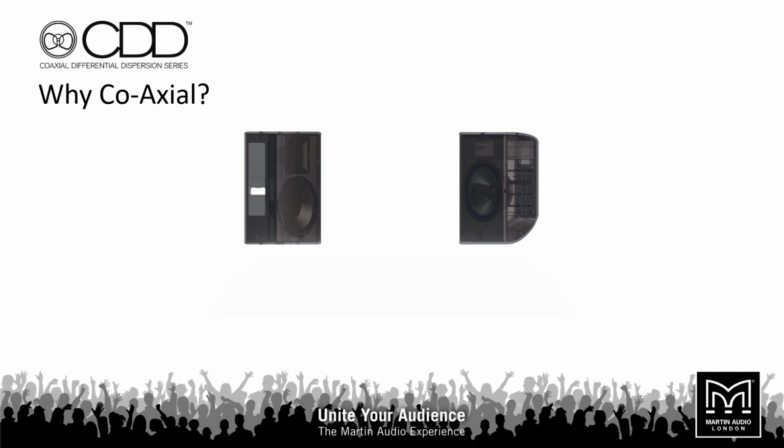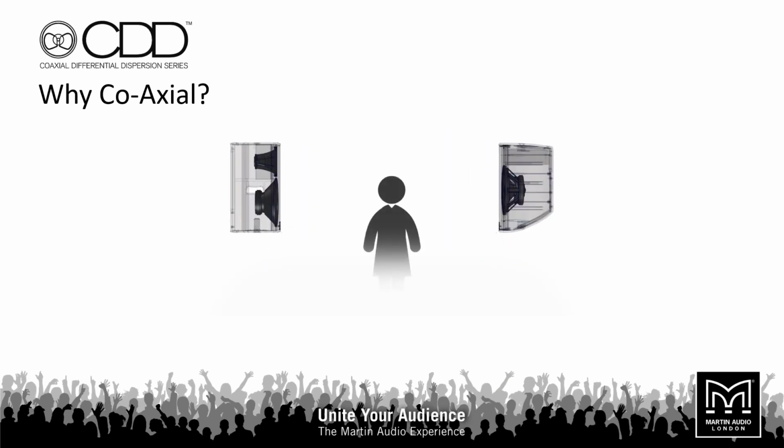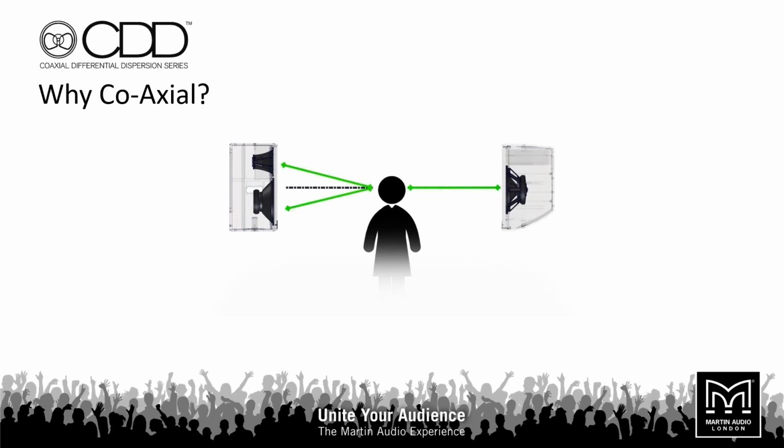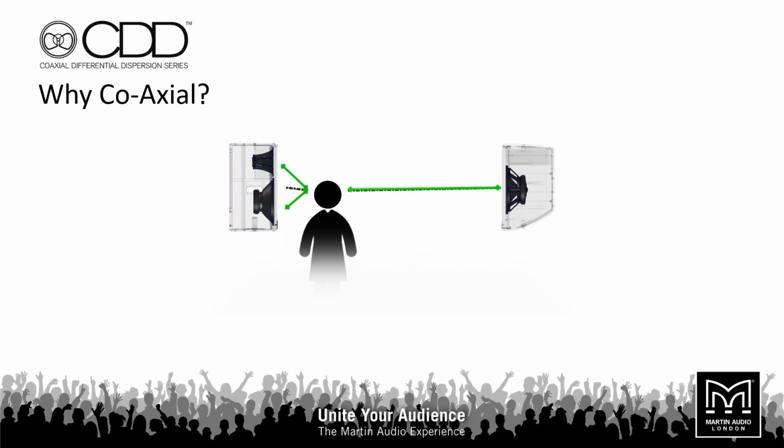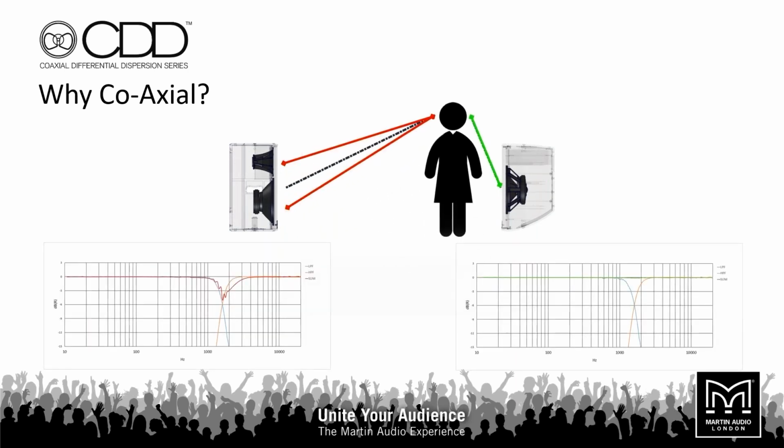And because they originate from two different sources in this crossover band, depending on your location in the venue relative to these loudspeakers, there's going to be a difference in path length or a difference in arrival time to your ears. And of course, this difference in time or path length is going to allow these wavefronts to arrive at a different position in phase, and therefore they're going to interact or interfere with each other. This is going to happen to a varying degree relative to where we are compared to the loudspeaker.